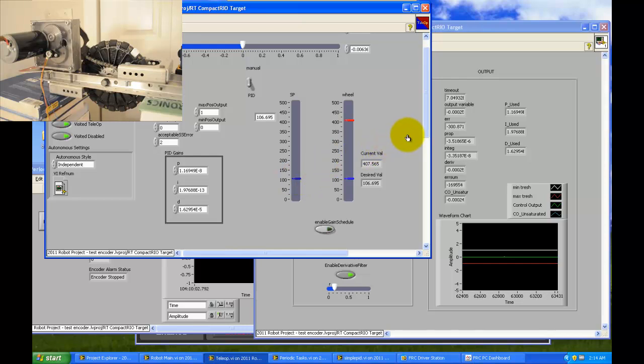The gains are so small that they're approximately 0. E to the minus 8, e to the minus 13, e to the minus 5. They're so close to 0 that when the calculation is being done, it's not within the deadband. So the value that the controller is outputting is so low that it's not even driving the motor. It's too close to 0. So no matter what you do on this set point, there is an error. You can see the error is there. The PID controller loop is working. Just the values are so small that your physical system is not being controlled.